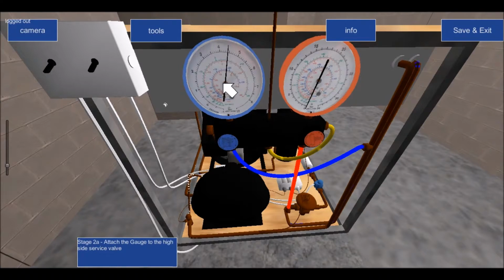And we're talking about very small volume of air here, so you don't really need to purge for all that long. So one of the videos that we put up was about purging, and some of the feedback and some of the questions that we got was, oh, well, we usually leave that, we give it a good old purge. It's not really necessary to prolong the purge. You're just giving it a short, sharp purge to remove the small amount of air that's in the lines. The air that's in the lines isn't all that great.